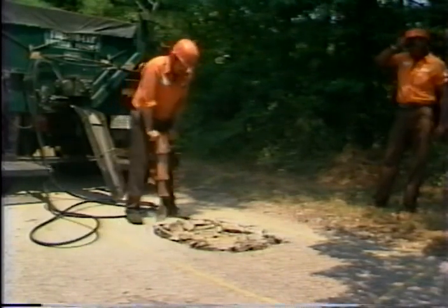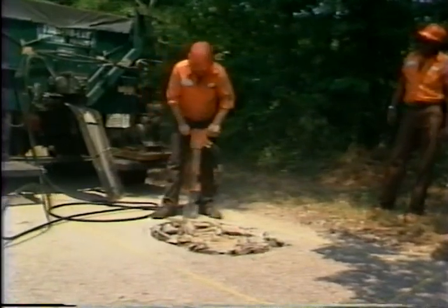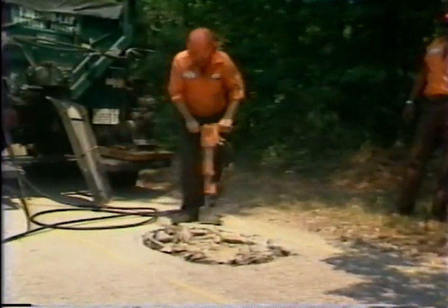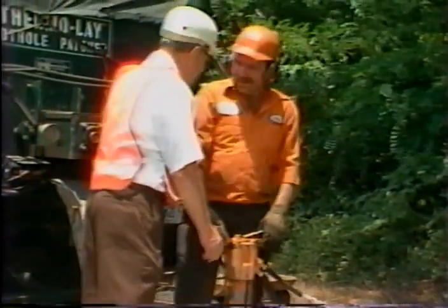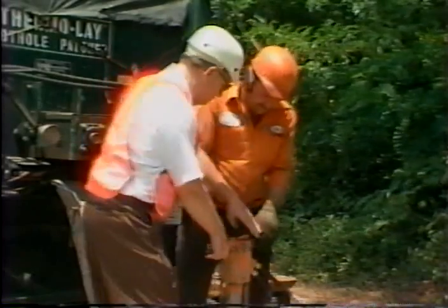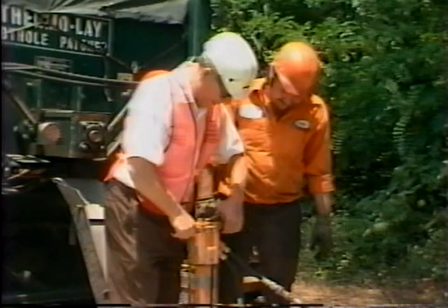Begin cutting near the center of the pothole, forcing the material in toward the center. Take care when using the pavement cutter not to rock it during the cutting operation. Rocking causes damage to the stable pavement, resulting in cracking.